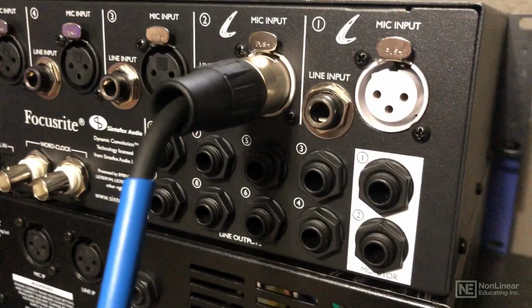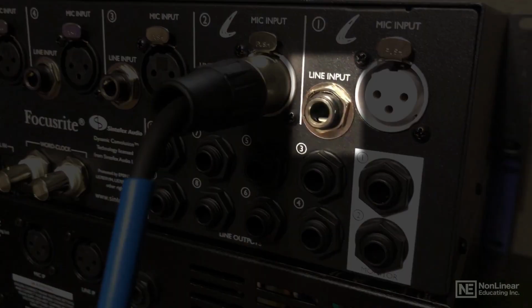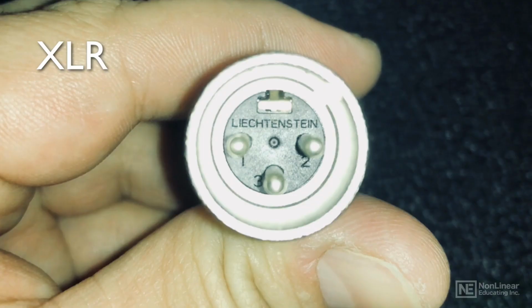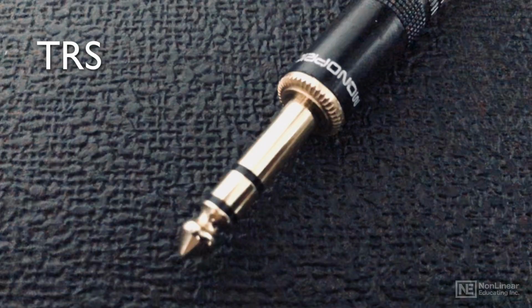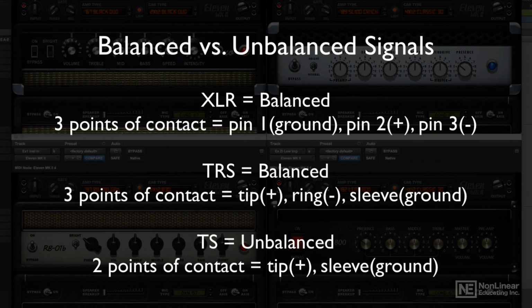Now, you don't want to plug your guitar or bass directly into a mic or line level input. It's not usually possible with mic level inputs because they typically have XLR microphone jacks, but line inputs are typically quarter-inch inputs. Mic and line inputs are balanced inputs, and they use balanced connectors like XLR and TRS, not unbalanced connectors like a TS connector on an instrument cable. TRS and XLR are both balanced and have positive, negative, and ground wires on them. This is why XLR has 3 pins, and TRS has a tip, ring, and a sleeve, so 3 points of contact. With TS connectors, there's just 2, a tip and a sleeve. Instrument cables work with unbalanced signals.